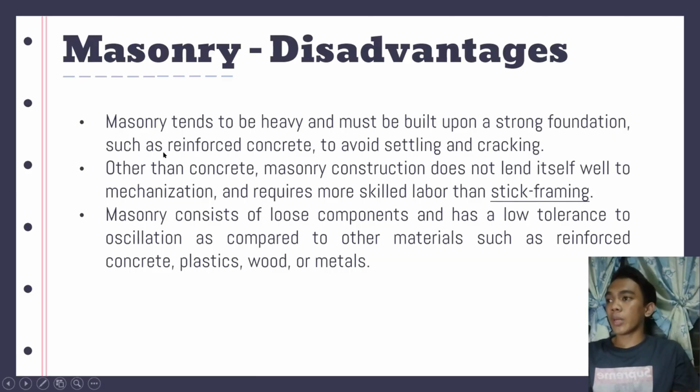other types of structures. Then next is, other than concrete, masonry construction does not lend itself well to mechanization and requires more skilled labor than stick framing. So it is not easy to do, and it needs a lot of skilled workers. And next is, masonry consists of loose components and has low tolerance to oscillation as compared to other materials such as reinforced concrete, plastics, woods, or metals.